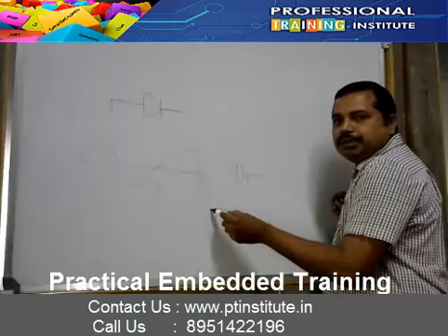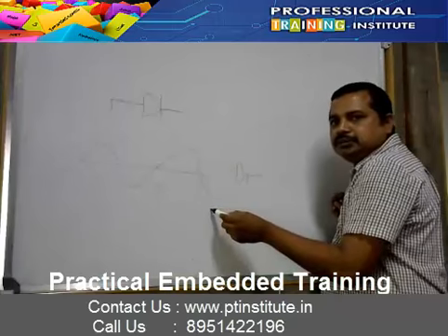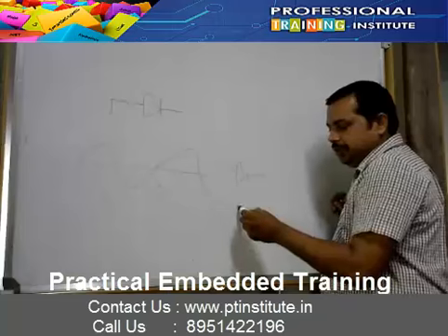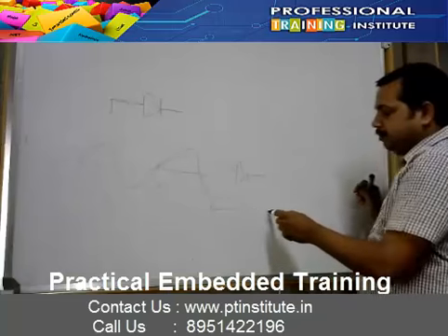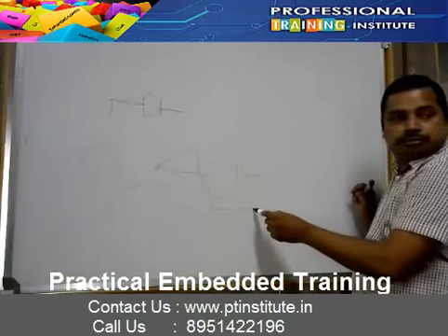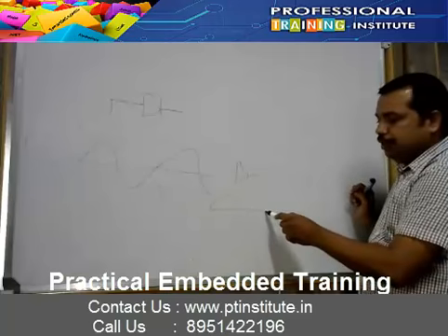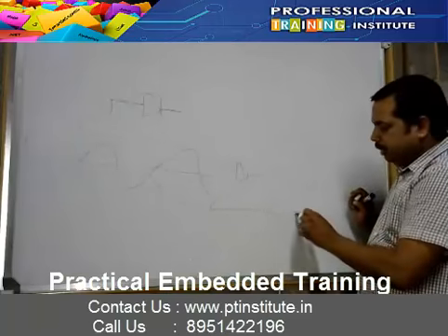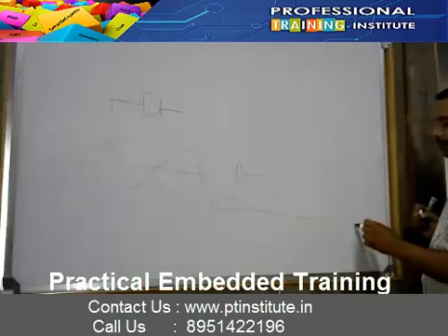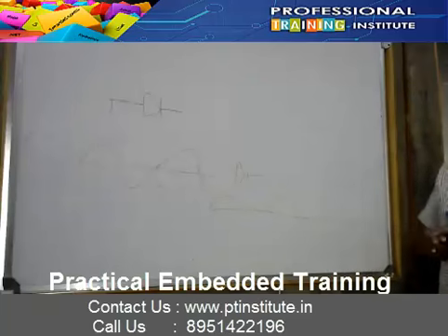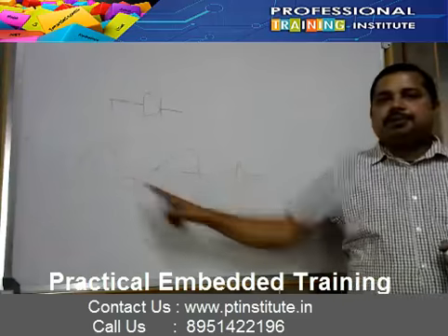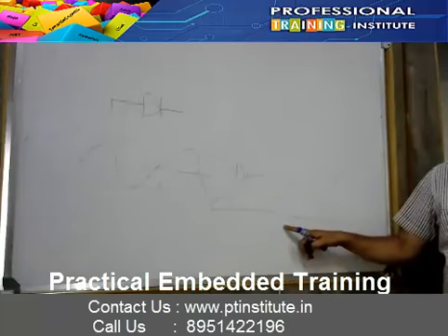Consider it is forward bias. What output will I get? Only positive, this I will get. What will I get for negative? No. And again positive like this. Again negative like this. Okay. So I gave this type of input and I got this kind of output.